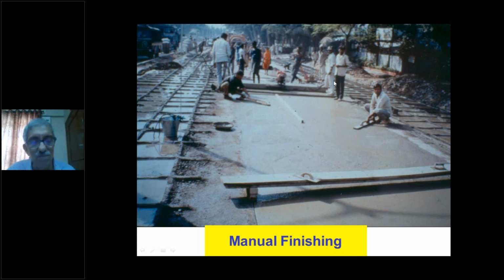They used to use a beam vibrator and vibrate the concrete on the surface. But this was a non-reinforced concrete, but still needed compaction because it was not very highly workable. They were having a stiffer mix. Again, it all depends on the specification.